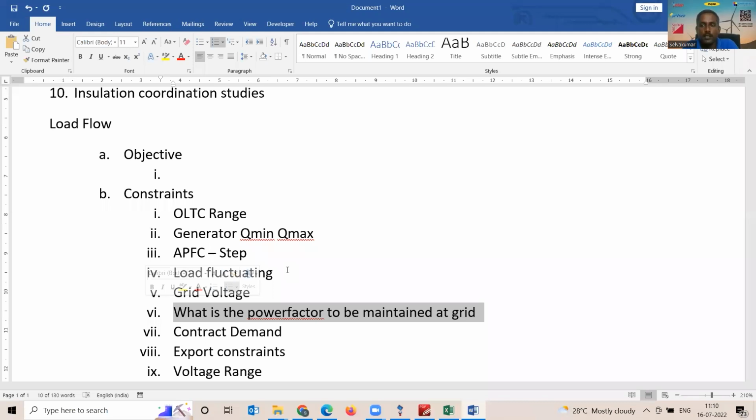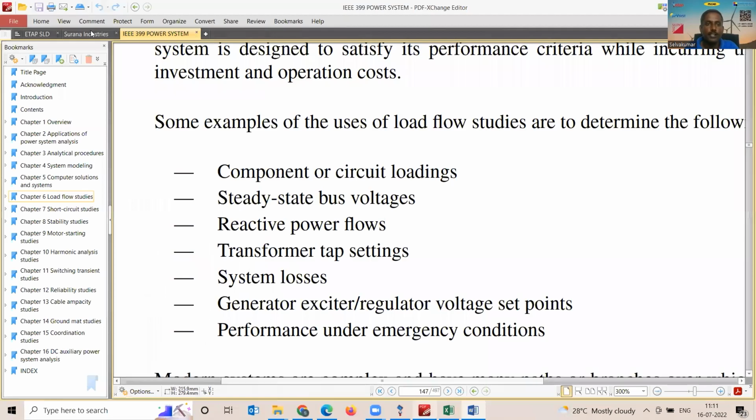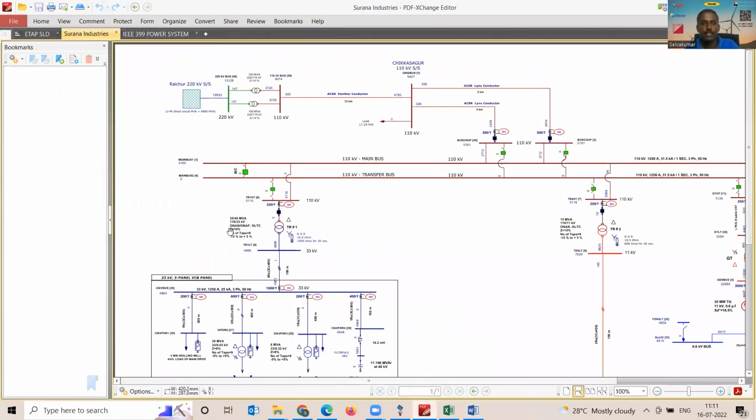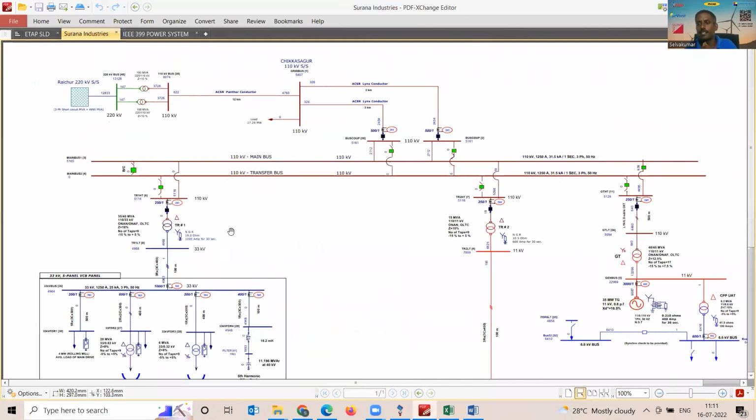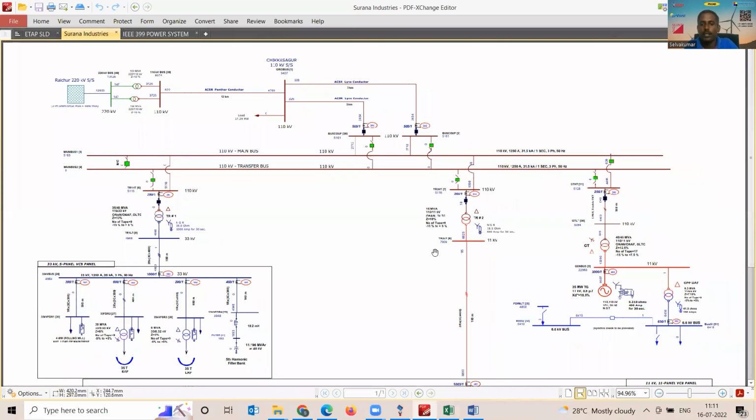Optimize your equipment, their ratings, their data sheets before procuring this equipment. That's the real reason why load flow is needed at the planning stage, not after construction of the industry. In 90% of the cases, we do load flow analysis for the sake of documentation at the verge of completion of the project or before handing it over to the customer.